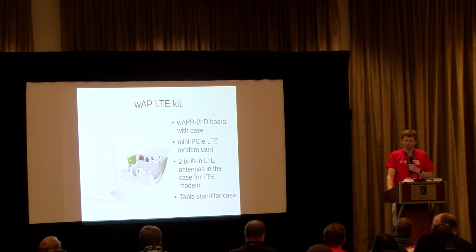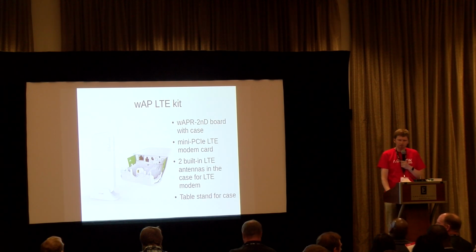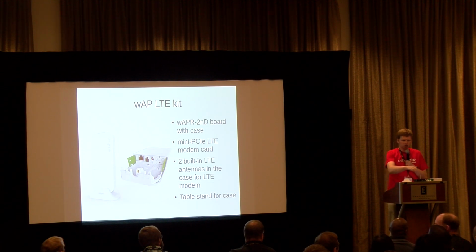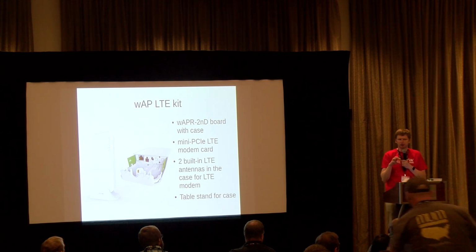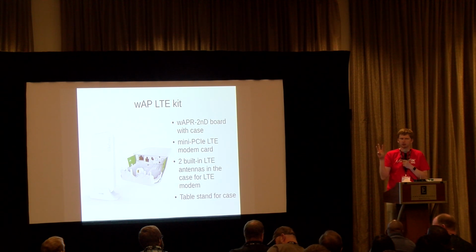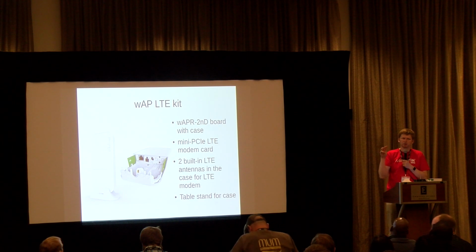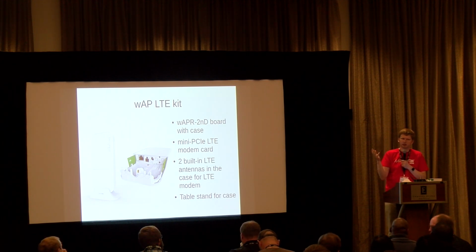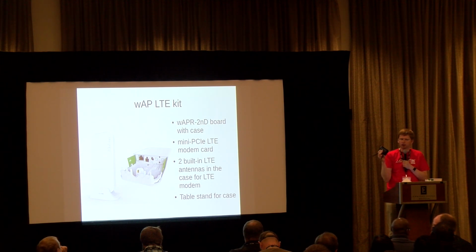I have two questions. One, you mentioned that GPS is external to the LTE modem, or internal? If I shut down the LTE, can I independently shut down the LTE modem to save power and still use the GPS output? For example, if you have an LTE card with GPS functionality, usually it has three connectors: LTE1, external LTE connector and GPS connector. Theoretically, depending on the modem, you can disable the LTE communication but still use the GPS by sending specific AT commands to the modem. But this board doesn't require an LTE modem for GPS, because the GPS chip is soldered on the board itself, so you can enable that GPS function there.